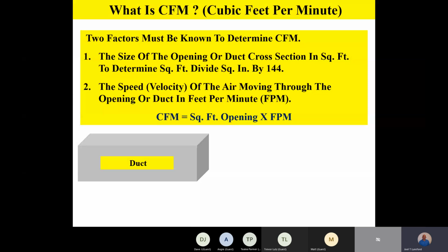And likewise, that same duct, if you take a look at the air duct calculator in that first little window we talked about, 500 feet a minute velocity and 500 CFM takes the same size duct. So the point is, based on velocity and the amount of air you're wanting to move, the duct calculator will tell you what size round duct it's going to take. And you can also see that that same duct, at different velocities, is going to provide different CFMs, based on what you're designing to. So any questions or comments on that so far?